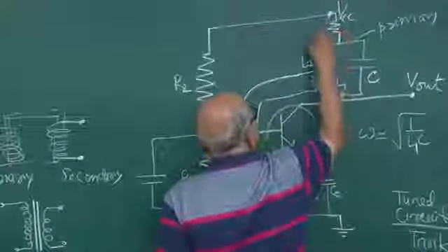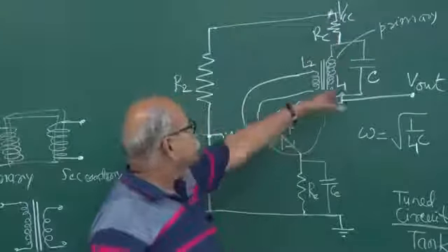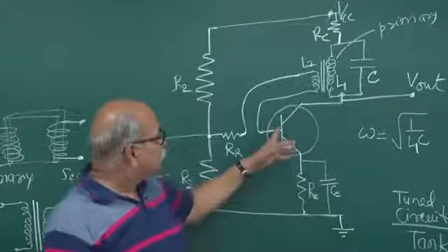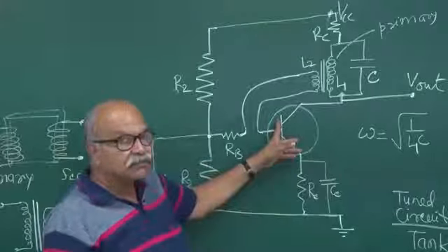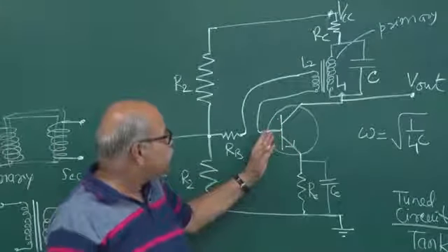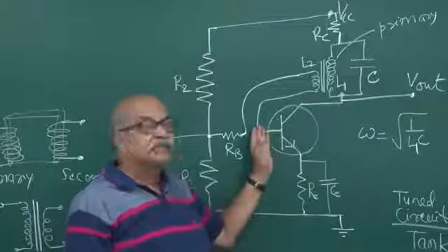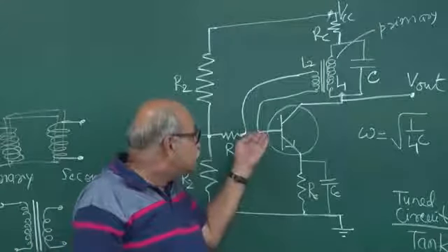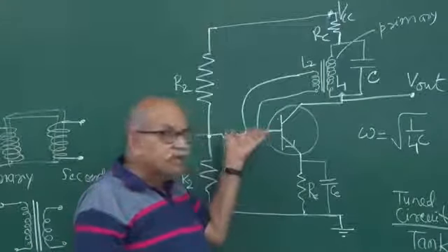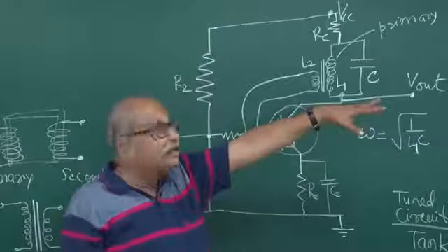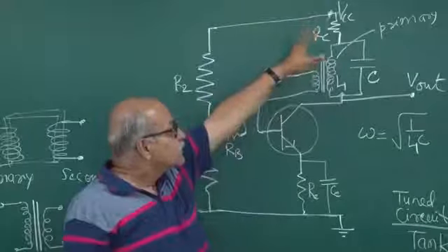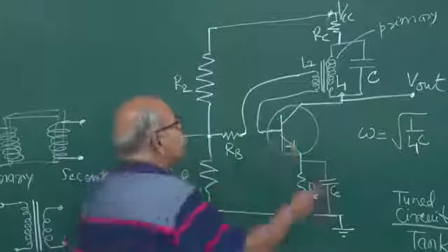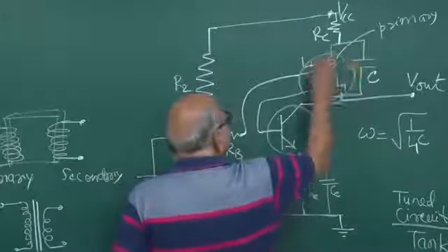So let us put a resistance and then connect it, so that this whole circuit is completed. So in that common emitter mode, when you do amplification, the phase of the output signal and the input signal differ by pi, right? Because if this base biasing voltage increases and current increases, then on the other side the current in the collector circuit increases and then the output voltage goes down. So there is a phase change of pi here.